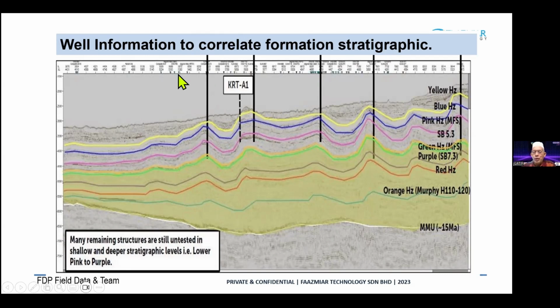But for offshore, you might have one drilling center here. Then you have one well going to the reservoir, and then you have a directional well going from the same drilling center to this target here, and then another well going through another center to another target here. So offshore, because it's very expensive to construct so many structures, we're talking about one main structure and multiple wells. From this structure, we're going to drill another well here, another well here, and here. So that's the strategy to reduce the cost.